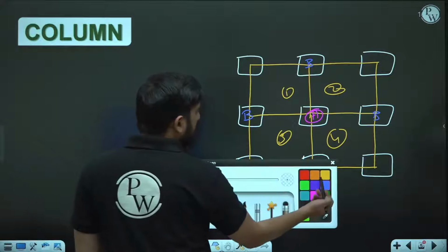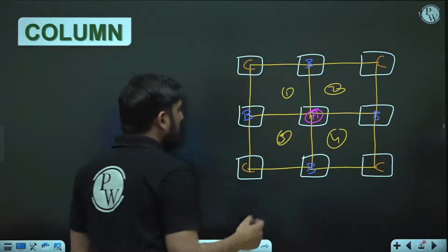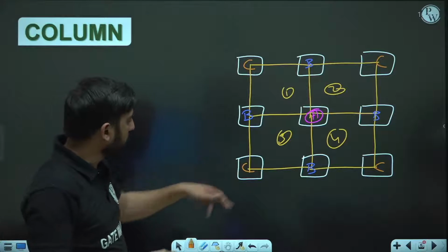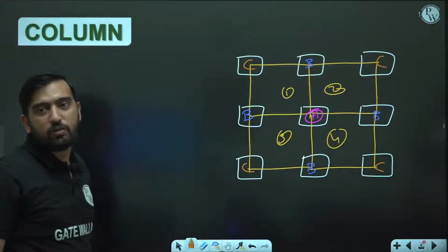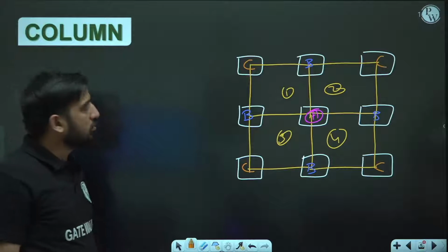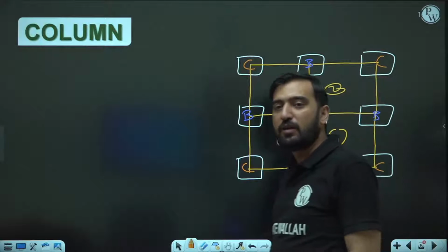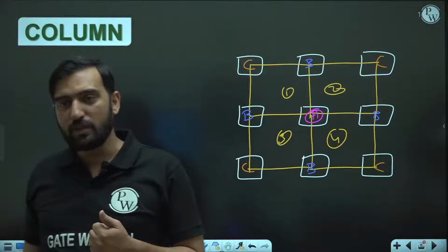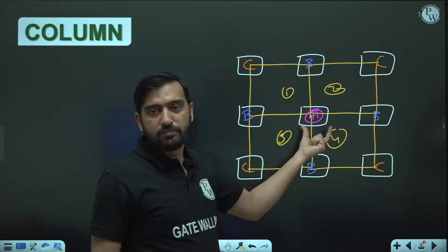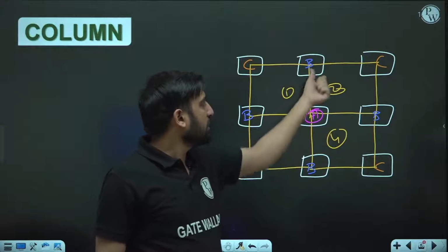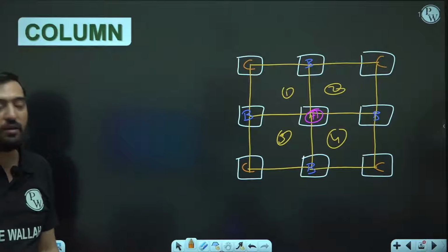And these extreme corner columns, let me call them C columns, are going to compress. Apart from that, they are going to bend in this direction as well as in this direction. So they are going to have dual eccentricities, and they are known as columns subjected to axial load as well as biaxial bending, depending upon the nature of loading. So these are the 3 major classifications of column: A, the axially loaded column, which is mostly our area of interest; this, the uniaxial bending column; and these corner ones, the biaxially bending columns.